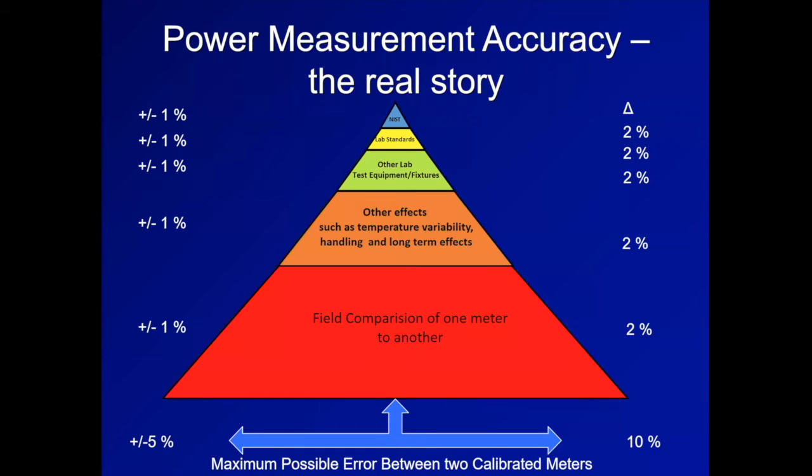And of course, we do that, and we calibrate the entire system. The next thing you need to know is that the directional coupler's coupled port output has a certain frequency response and a certain output level, and you need to know that with a very high degree of accuracy in order to marry that up to the sensor so that you know what the actual power output is.